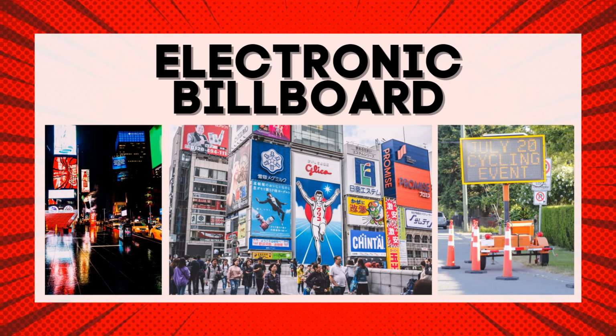Some of them are classified as electronic billboards, in the form of large LCD or LED screens that can display digital advertisements or announcements just like television. They are now widely used since they are very flexible, as they can display multiple ads in one location. Our activity for today is to develop a mini electronic billboard using an Arduino board and a small LCD screen. The LCD screen supplied has 16 columns and 2 rows, for a total of 32 characters. Our objective is to display our own announcement on the LCD screen.